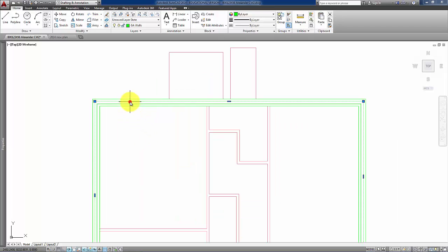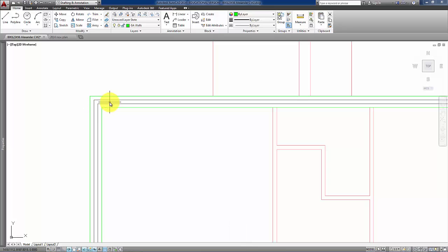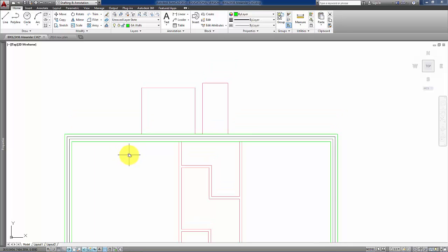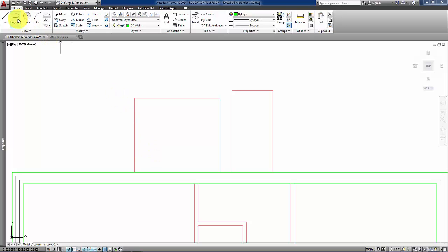Now what we can do is go back and choose the internal two wall lines and move them over to the Walls Cavity layer. So you'll see they now have a different appearance. They're grey, but as well as that they will print out thinner lines. The two outer lines will print out thicker. For the rest of the external walls then, we need to draw another little polyline just at the top here around the outline of what is the utility room.